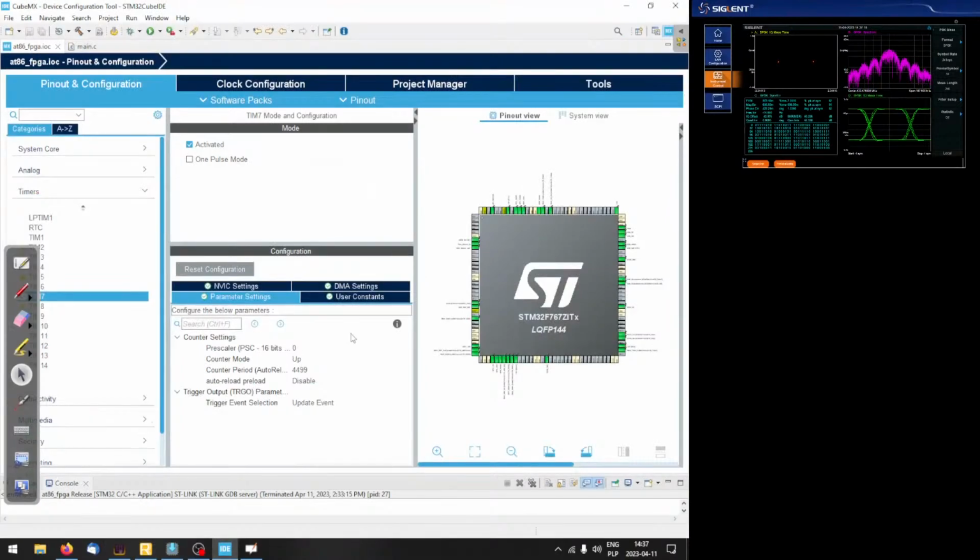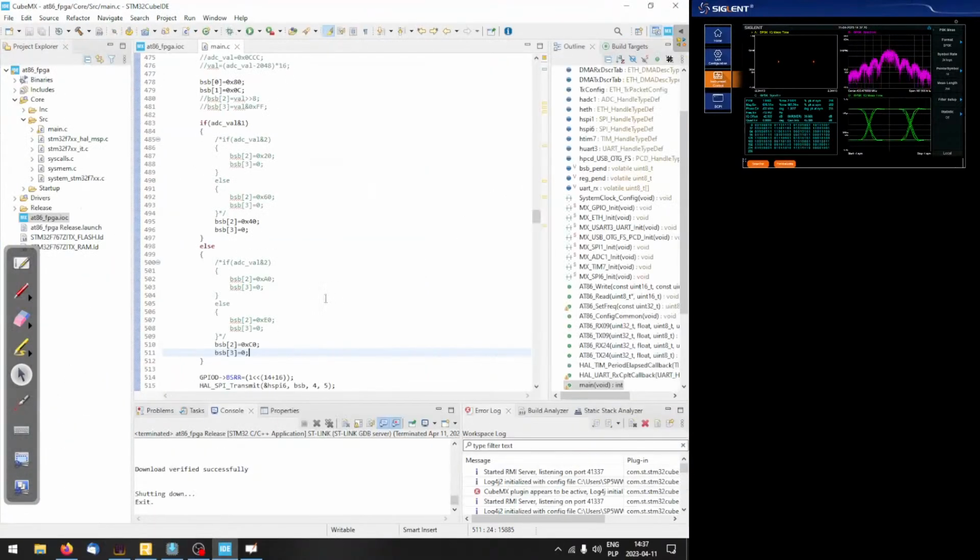So let's get back to the C code, and let's actually try and transmit some QPSK. So if we switch to the QPSK demode, you can see that the 2 points just wiggle randomly, and that's because the instrument is actually trying to align the phase with what it expected to be, and that's not going to happen because there are not enough phase transitions for it to lock.